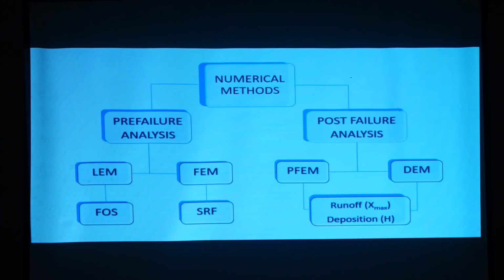And these numerical methods contain pre-failure analysis and post-failure analysis. In the pre-failure analysis, we have used the limit equilibrium methods and the finite element limit methods. The limit equilibrium method determines the factor of safety, a deterministic approach, and the finite element method determines the stress reduction factor. And in post-failure analysis, I have used the PFEM. This PFEM determines the runout distance and the deposition height.